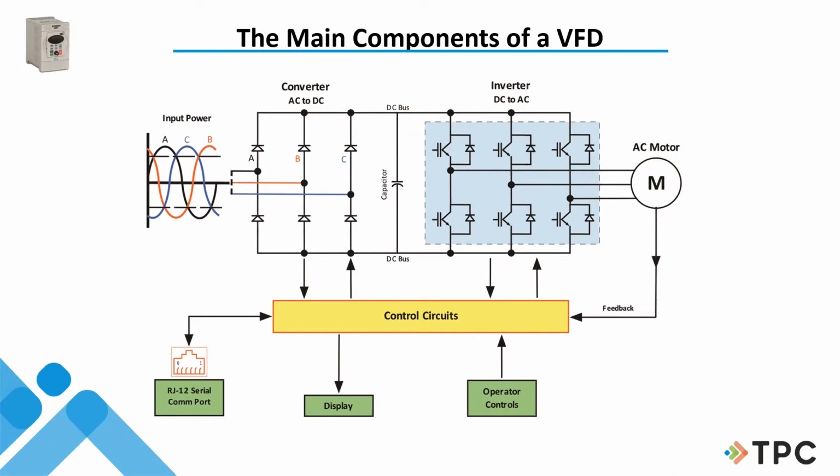It looks pretty ragged as far as a cycle or waveform if you have an oscilloscope, but it will look like a waveform, and it has to because we're on an AC motor. Now, some motors have what we call tach feedback into the controls to let us know how fast that motor is really going. So we told it to go some speed, and we're going to get some information back into our controls.